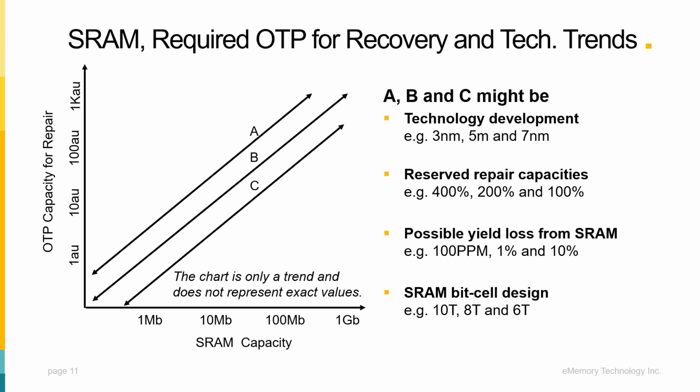This trend is closely linked to advances in process technology, expected yield performance, and the design of SRAM bit cells, and it causes the trend to move up and down, which I illustrate with lines A, B, and C.